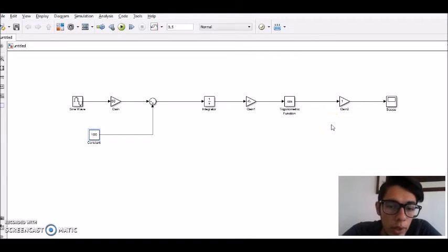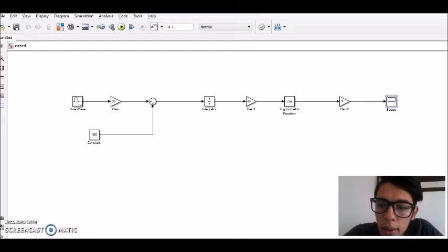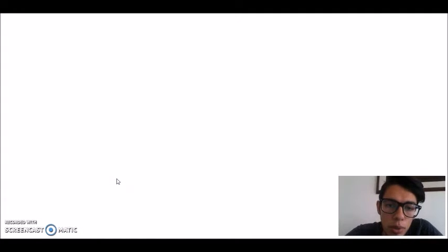Finally, to show this, we use a block diagram that simulates an oscilloscope. We press play to run the whole process, and when the program finishes, we double click here on the scope. So it will open a window with a graph and the signal. So double click, and it shows the final signal.